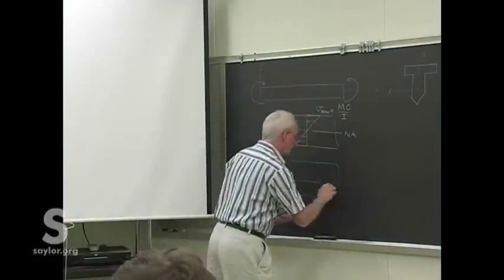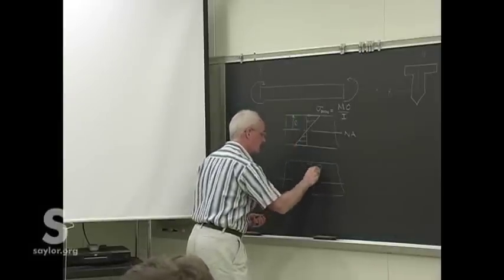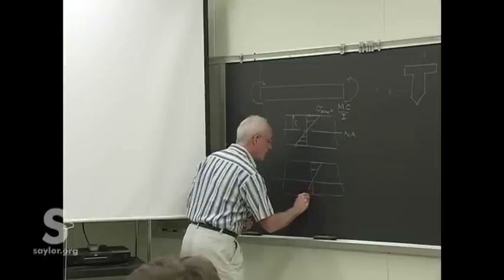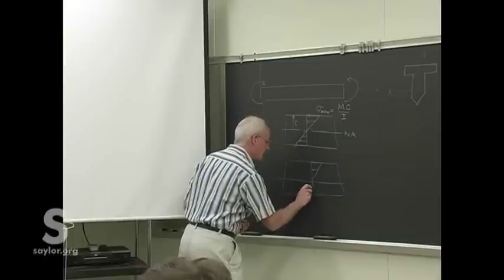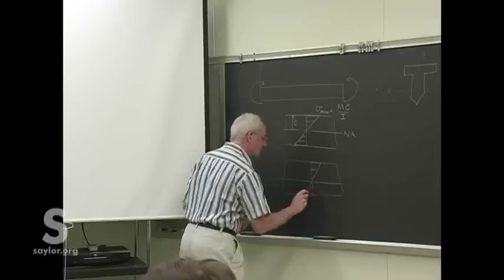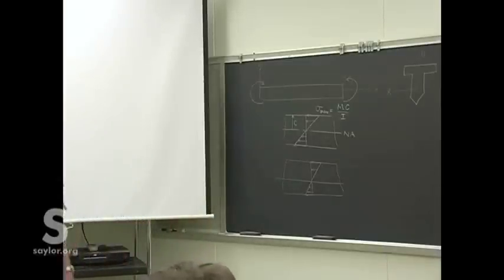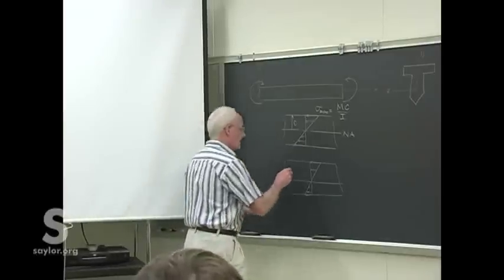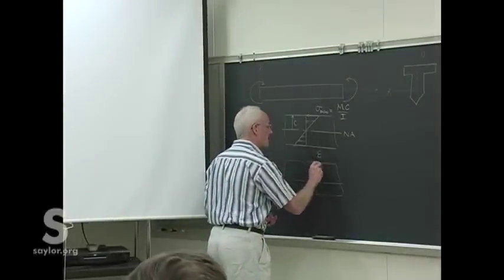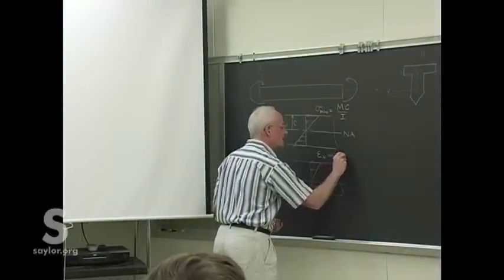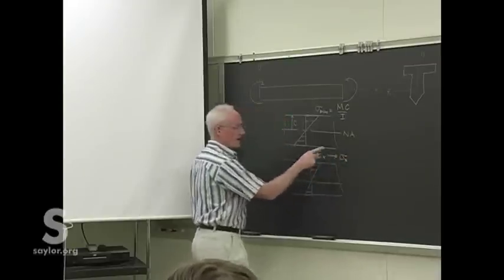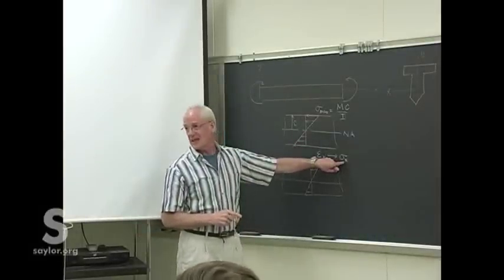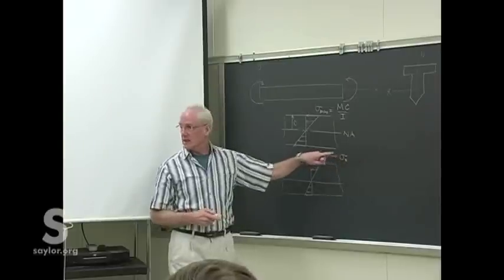However, because our material is homogeneous and isotropic, which means it's the same material throughout, same density, same material properties, everything, the strain distribution, which we found first to be linear, led to the stress distribution, sorry, other way around. The strain distribution is linear, and the stress distribution is also linear because they're related by a constant.